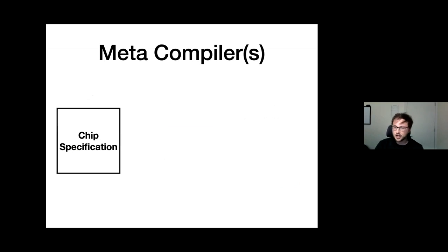So let's talk about meta-compilation in the context of hardware accelerator design. Note that the next few slides are abstract to arbitrary accelerators, then I'll bring it back into what we're actually doing. So first, as input to your meta-compiler, you provide some sort of chip specification. This will basically include all the possible parameterization of your particular family of accelerator. For example, number of levels of memory hierarchy, size specification of each memory, what compute resources you have, interconnect, all that stuff. And in some sense, this is just a high level list of all of the design decisions that a chip architect would come up with when designing a new chip. And the interesting thing is if we keep all these decisions as essentially free parameters in a programmable fashion, we can potentially develop meta-compiler flows.